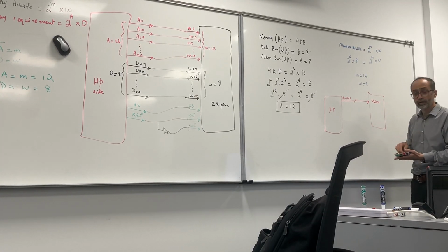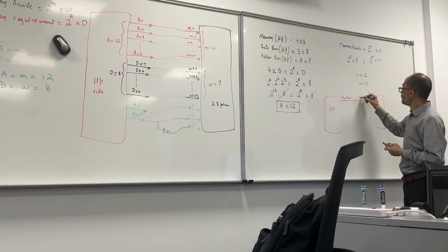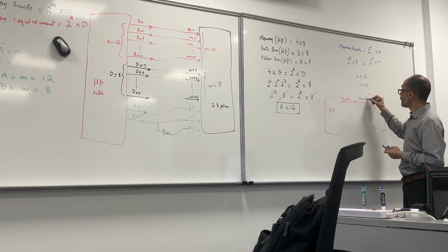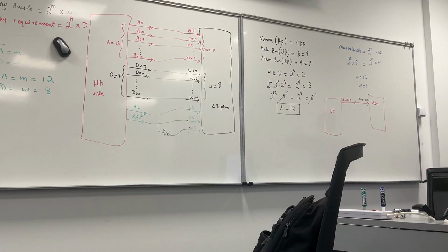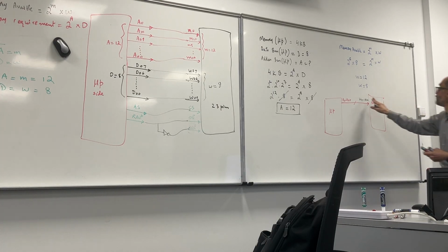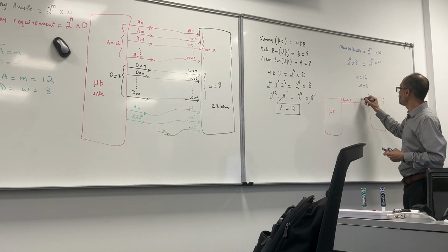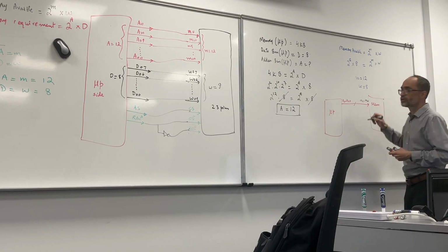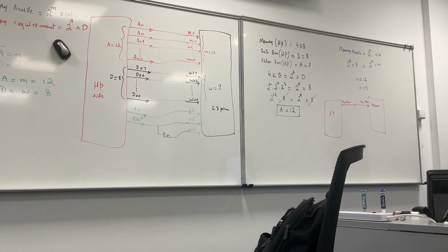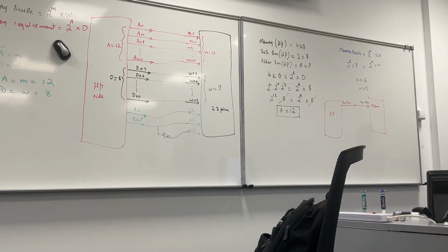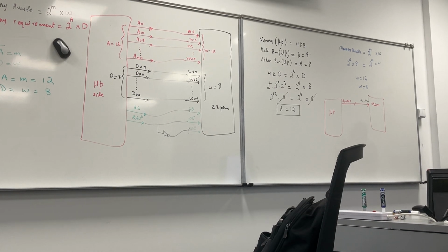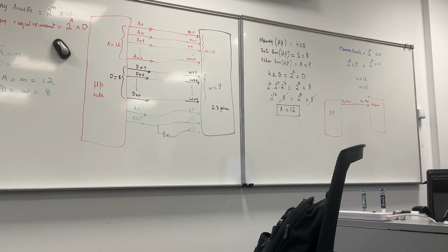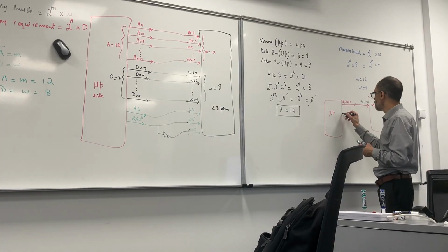It will be connected to what? W11 to W00 on the memory side. Sorry, not W, M11 to M00. This implies that A11 is connected to M11, A10 is connected to M10, and so on. These are the multiple lines, so this is a more compact representation. If the number of address lines is large, you have to draw it this way. Okay, now we have the data lines.